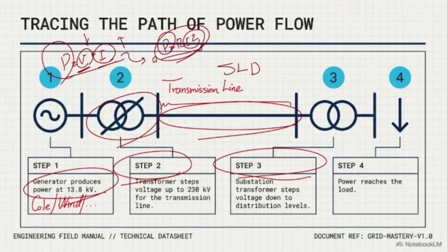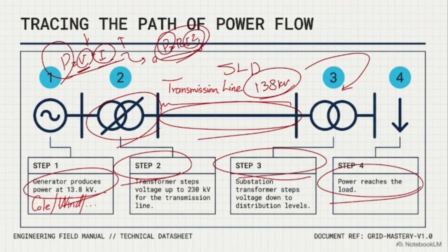Step-down transformer means that we do have a high amount of voltage, imagine 138 kV, and then obviously you have to reduce it down. So this step-down transformer is going to be in your substation. And at the end of the day, you do have another kind of transformer that is going to be in your alley, in your street, and those are going to convert that voltage. That distribution part can reduce it way down to something around 120 volts per phase in order to use it for day-to-day life.